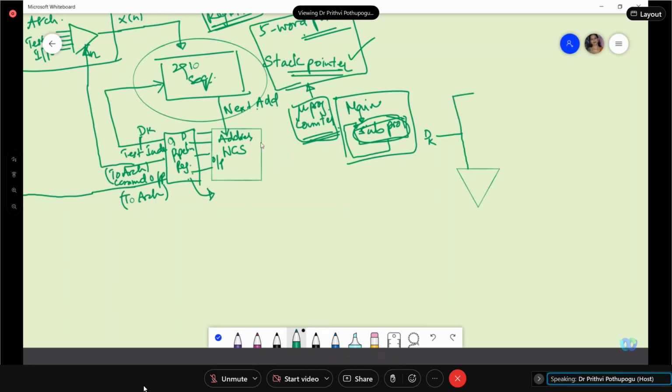Parallelly, you can store that in the registers I mentioned, and through that, that means some return address, if you need it, you can access directly or through registers. And if you have a stack pointer setup, through that the interrupted calls or interrupted addresses can be taken. So this 5-word stack will be available on your microprogram sequencer.